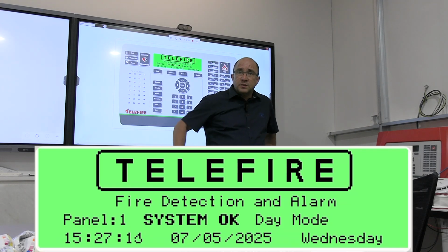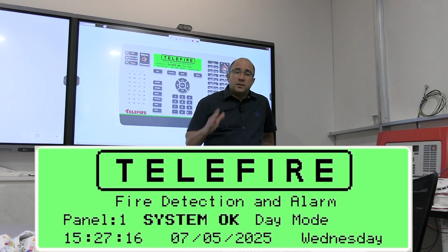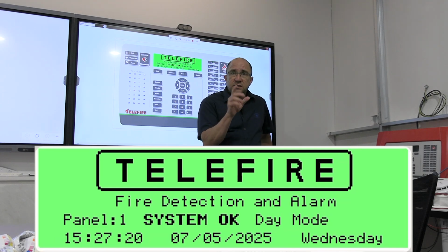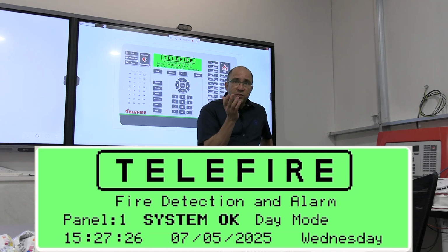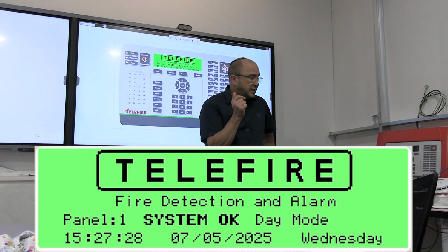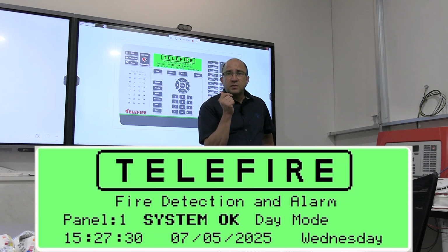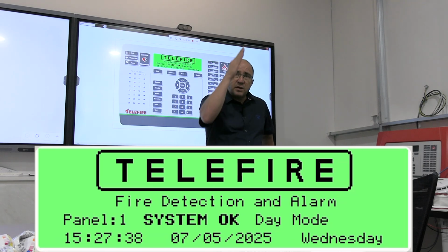You have 3 options: 1, Wi-Fi, 1, TCP, 1, SIM card. The only problem, maybe you understand computers, so you won't have that problem: you have to open port 8883 on your router. Okay. Because that's the gate to Amazon.